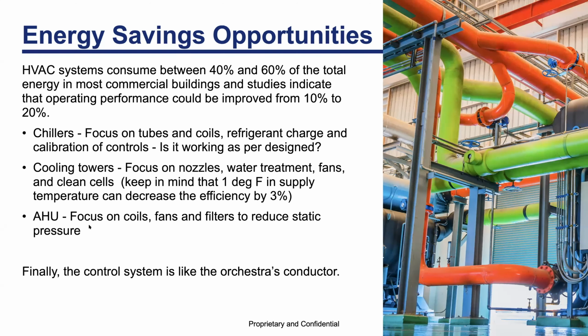So to increase from MERV 8 to 13 or even 14, this of course brings an additional static pressure that we must evaluate. Some equipment, RTUs, rooftop units, some air handling units are able to handle the extra pressure, but quite frankly, others cannot. So we must make sure that the fan and the motor that we have can handle the extra static pressure.